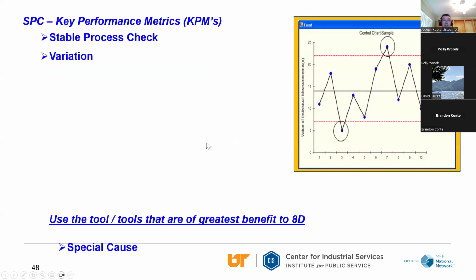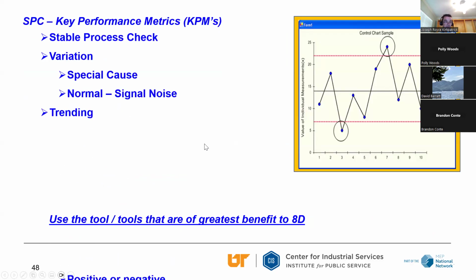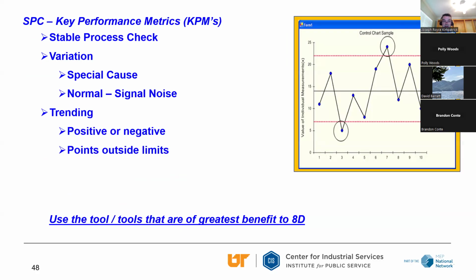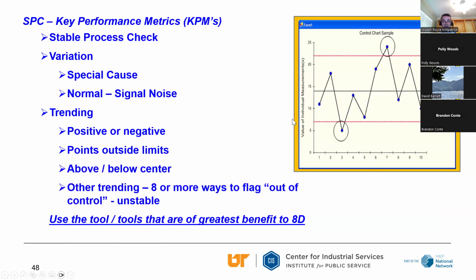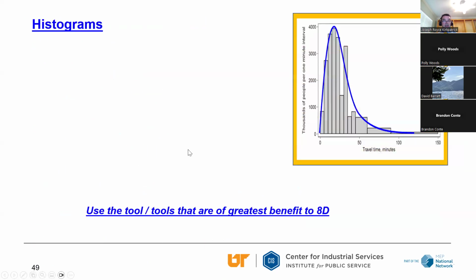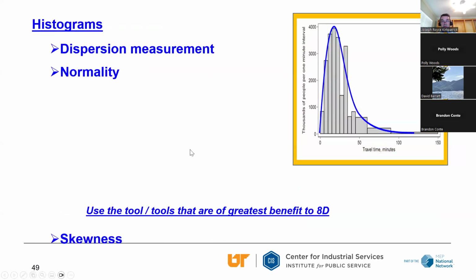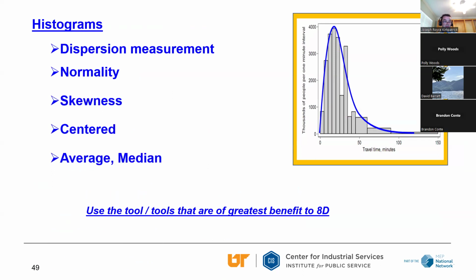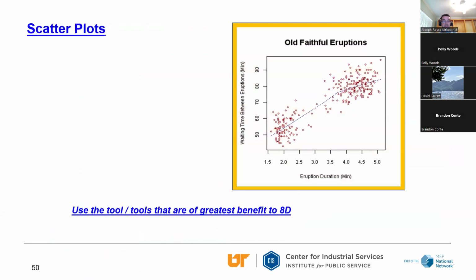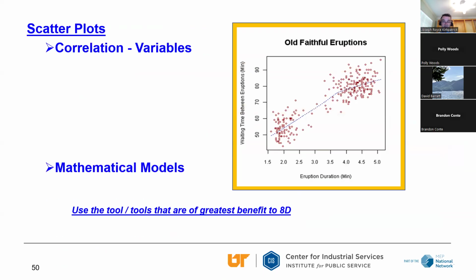Others are SPC charts, looking at the stability of the process and the variation that's going on, to help identify trends. Anything that's outside of the control limit is abnormal, because statistically that should not happen if your process is stable. If your process isn't stable, the data is probably off. Histograms are another way of displaying data that's sometimes useful. Scatter plots are just plotting a correlation.